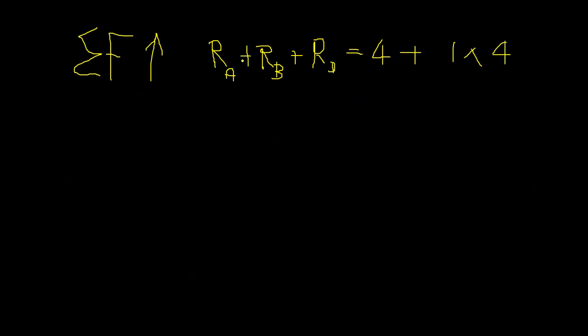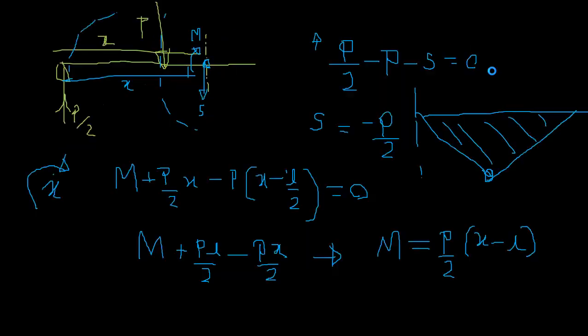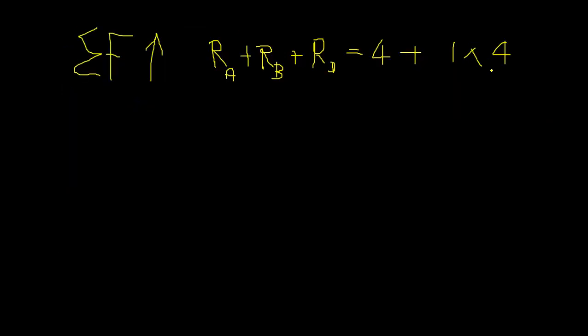So this is, horizontal loads equal to horizontal, vertical upward loads is equal to vertical downward forces, right? So you can write RD is 2, right? So RA plus RB is equal to 8 minus 2, that is 6 kilonewtons, right?